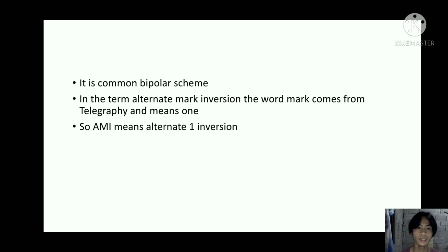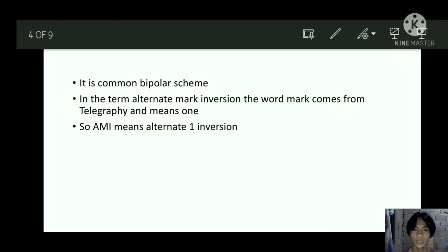AMI is a common bipolar scheme. In the term alternate mark inversion, the word mark comes from telegraphy and means one. So AMI means alternate one inversion.